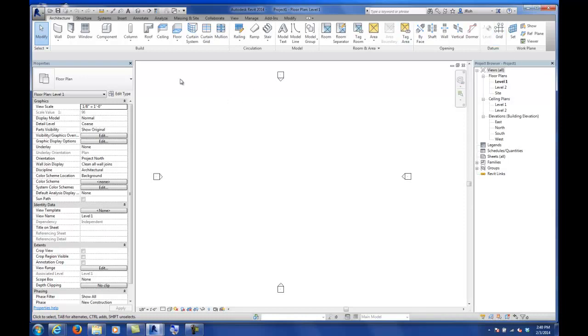One thing I just want to note, before we get into drawing with walls and so on, is that at any moment you can bring in image files as an underlay, and you can also bring in CAD files. So if you happen to have a CAD floor plan, or if you're working in Rhino and extract a section or extract a plan, as long as it is a DWG file, you can bring it into Revit and actually trace on top of it.